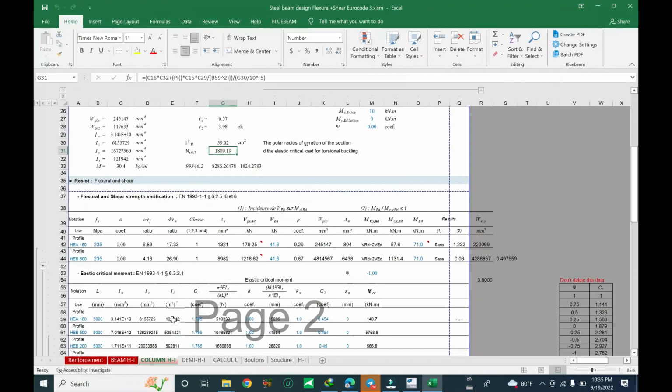The yield strength is 235, and the loading is pin with distributed load. Destabilizing load. We should classify destabilizing or stabilizing load because our beam is an unrestrained beam. We only have the support condition, pin, so the compression flange can freely rotate sideways and also rotate about its own axis. In this case, we should design as the destabilizing load and load applied at the top.